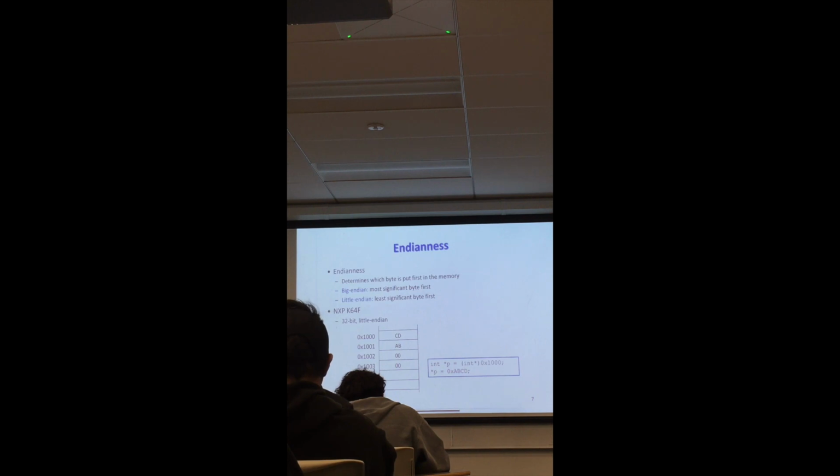So if I were to write only an integer, but I can also declare an integer to be long, which is 64 bits. In order to write 64 bits, the CPU will write first the 4 lower significance bytes, followed by the upper significance 4 bytes.